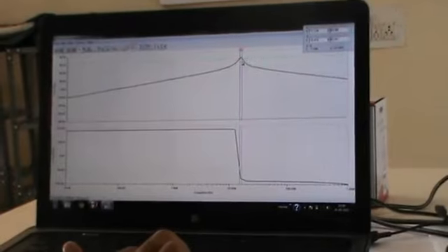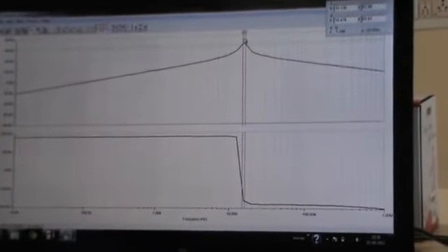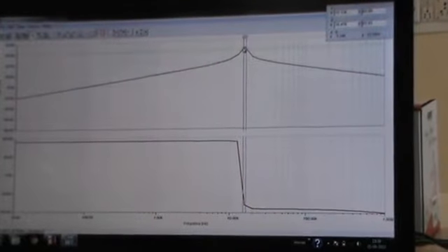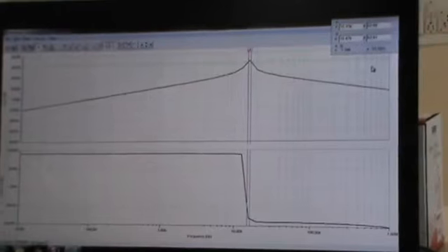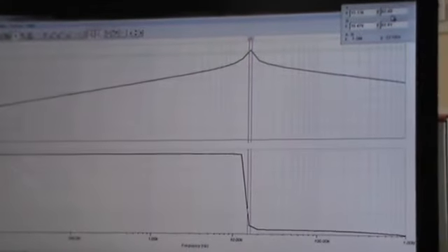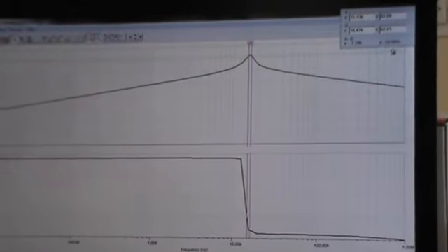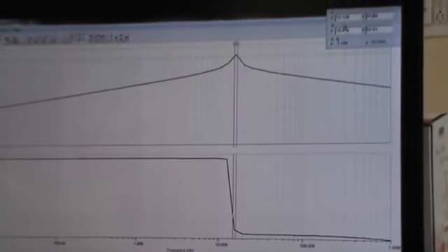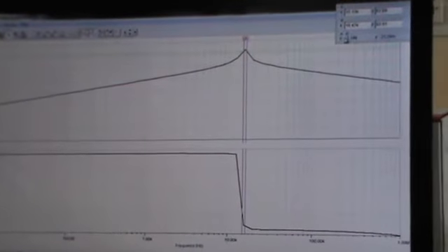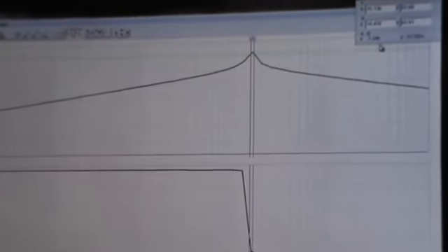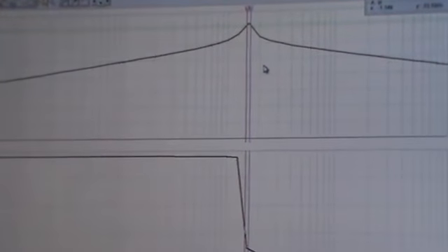Now here, for determining the gain bandwidth product, we have already taken it. As you can see, we have calibrated it to the 3 dB down frequency, and we are getting the gains as 62.88 3 dB down, and the frequencies are 15.13k and 16.47k. So that gives a bandwidth of around 1.34 kilohertz. So that is the bandwidth we are getting in this plot.